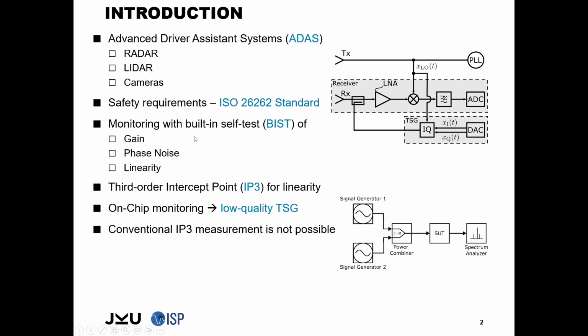And for on-chip monitoring, we unfortunately only have low-quality test signal generators. But for the conventional IP3 measurement, it is mandatory to use two signal generators with very high quality, because otherwise the nonlinearities from the test signal generator are visible in the nonlinearities from the system under test.